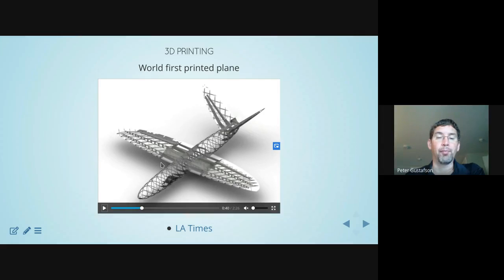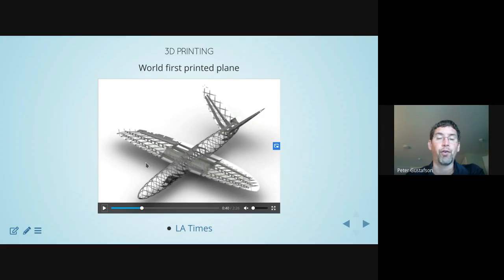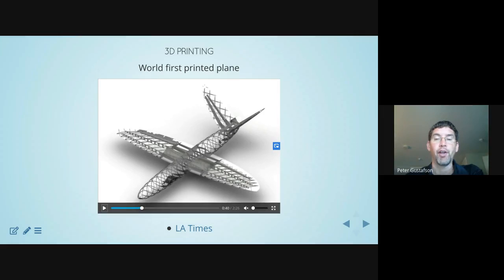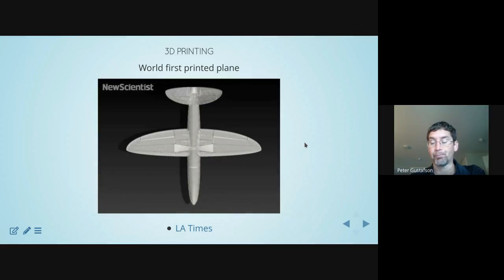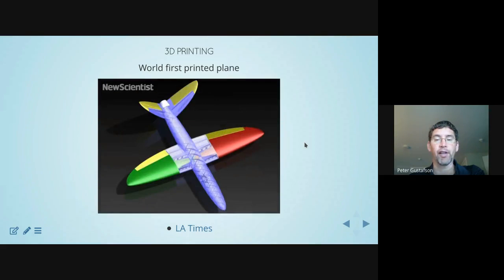So that makes them more efficient at carrying the drag loads, the shear loads associated with lift generation. And further, the fuselage has this helical wrap to it, and that allows the fuselage to be much more stiff with regard to torsion than it was previously. And that, again, would not be very practical in a larger manufacturing setting, but it's something that 3D printing can enable.